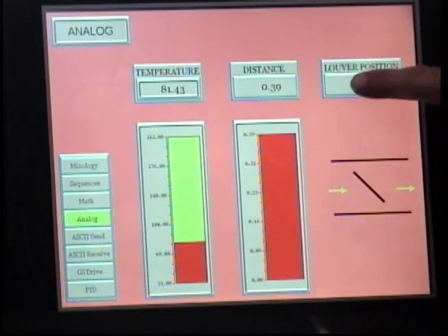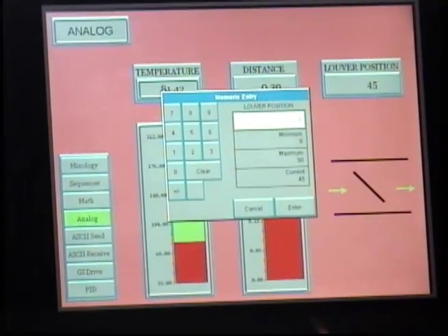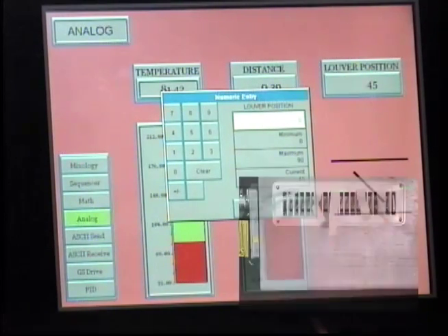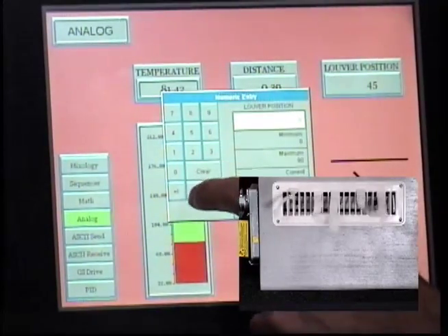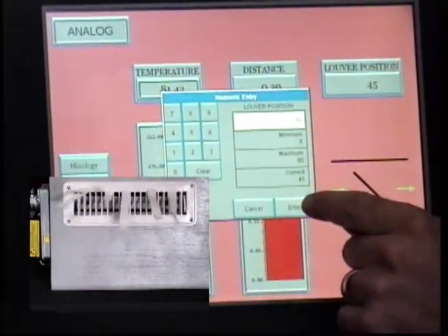And then finally, we have a damper control. We're controlling with a 4 to 20 milliamp output from an analog card. If they'll go back down to there, you go. Look at that. Right now it's at 45 degrees, so it's basically half open.